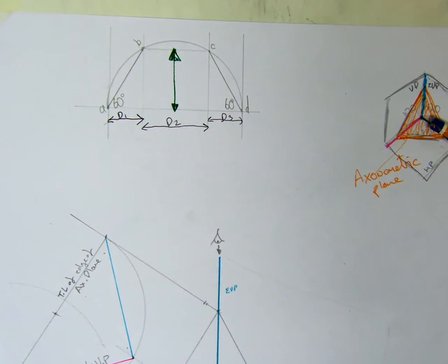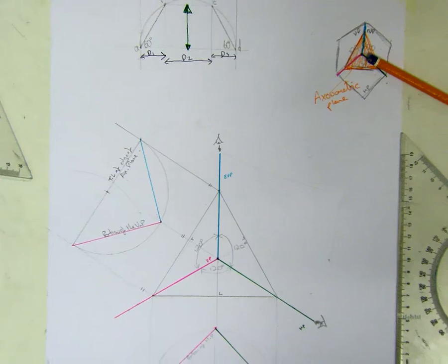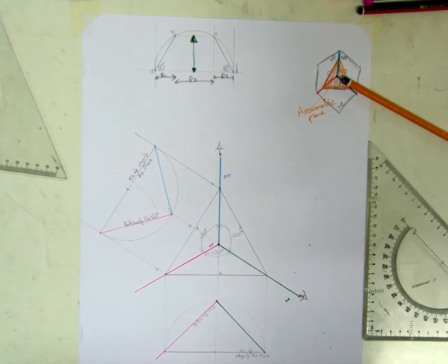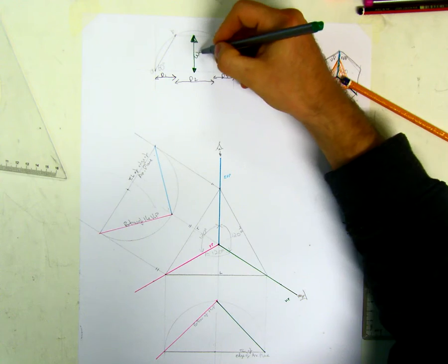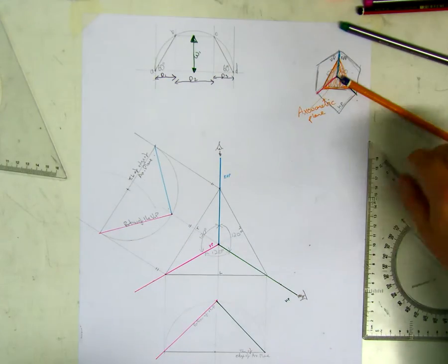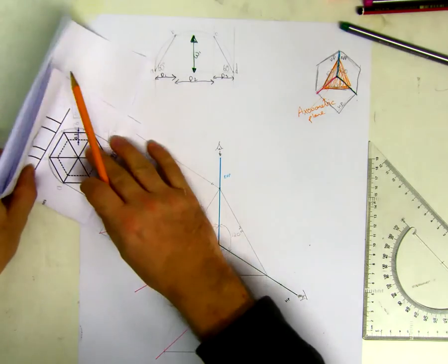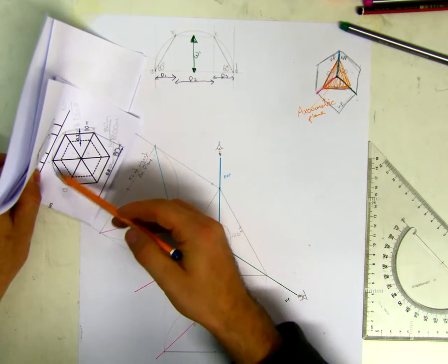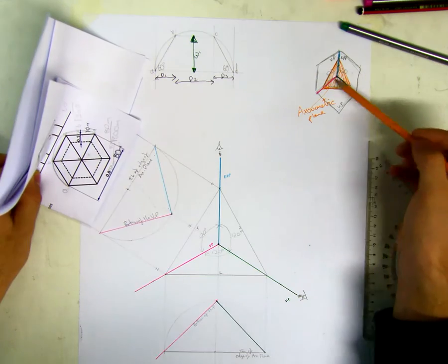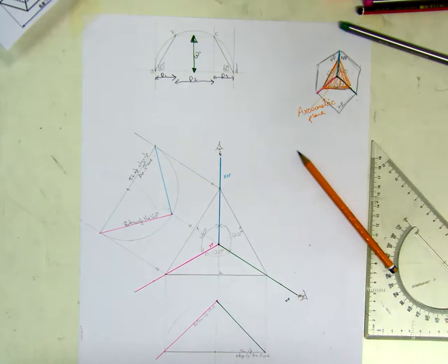Okay, so I'm just going to zoom out. Hopefully everyone will have no problem seeing this. This distance we'll just call W, because it's half the width, so W1. If we stuck our plan up against the horizontal plane, that edge BC would touch the vertical plane. So that's how we start the question. We have the distance there, and we're going to use our compass to take that distance.